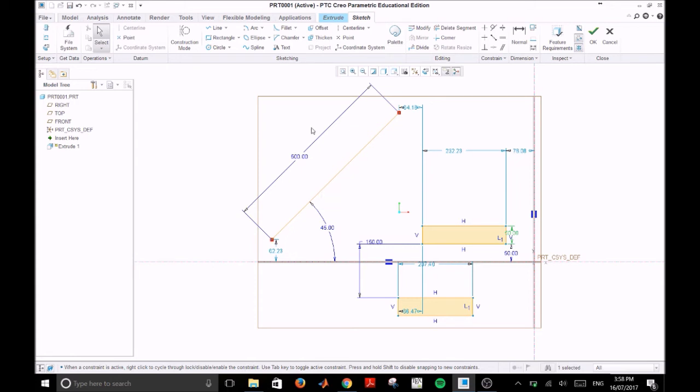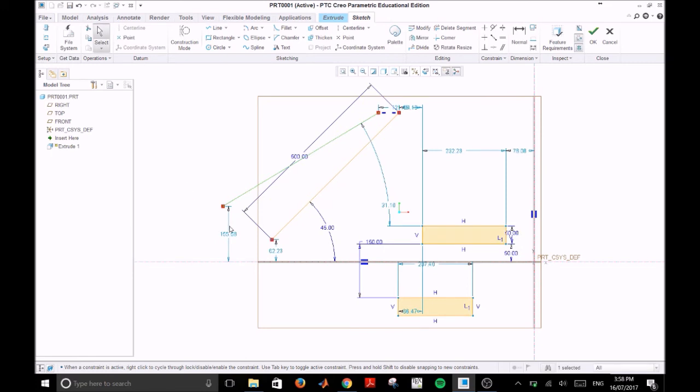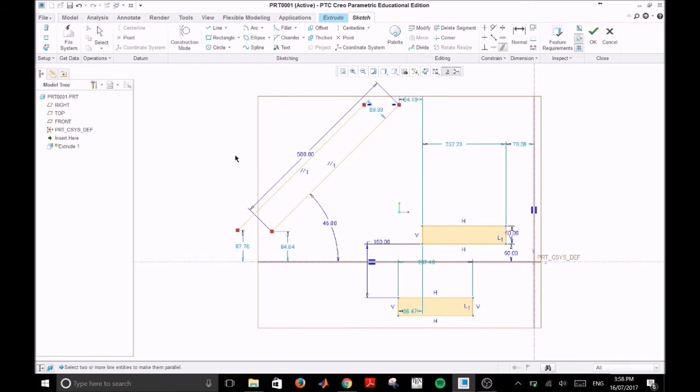Generally, Creo will add constraints. So if I wanted to draw another line starting at this point, so they're vertical, it would snap to becoming parallel. And you can see that those lines are parallel. If that wasn't parallel, we wanted to fix that, we could go in our Constraints tab. We can select Parallel, select our first line and our second line, and they have been made parallel. If we were to change the angle of the first line, the second line would follow suit.